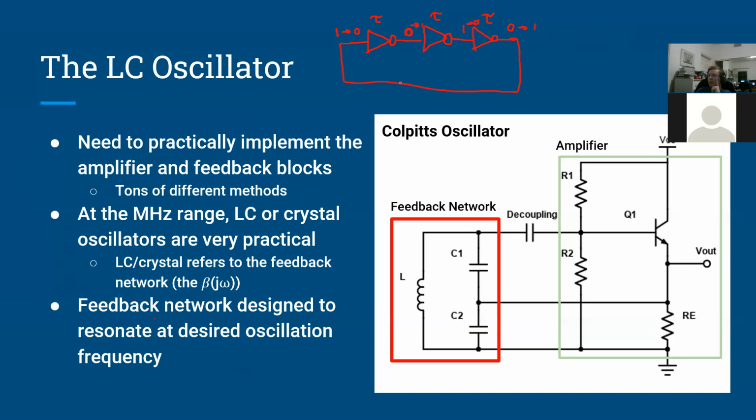You can think of the feedback path, beta, as just being 1, because we're just taking the output and feeding it back to the input and not doing anything to it. So beta is just 1. And then the gain, well, if you think of these as having a gain of -1 and some phase, because there's a delay.